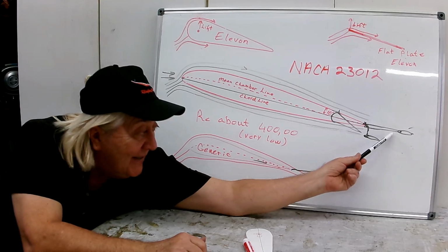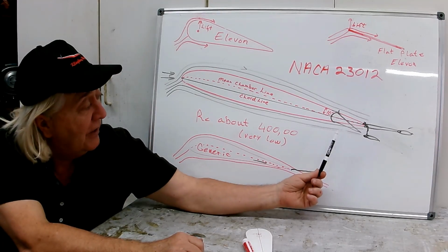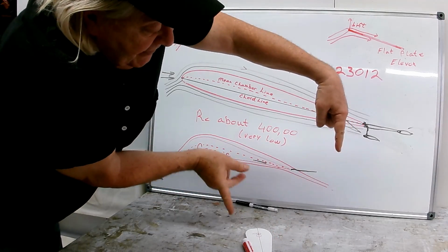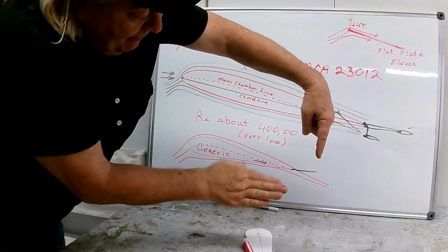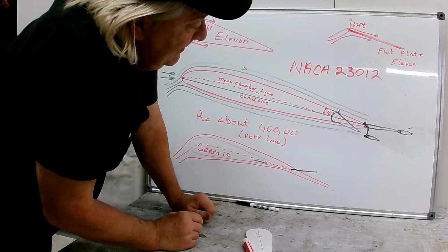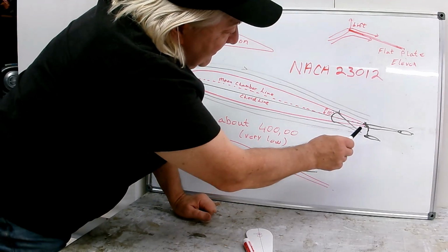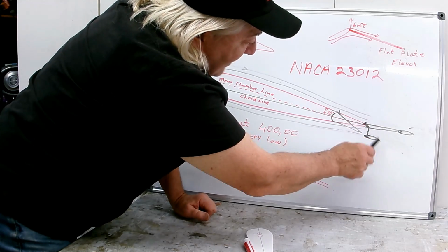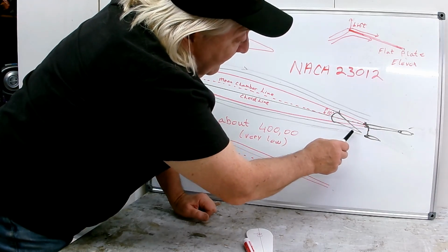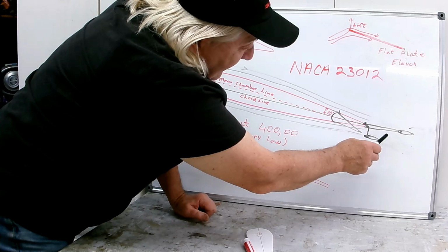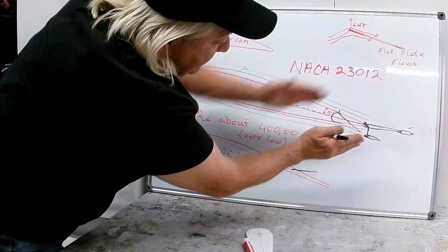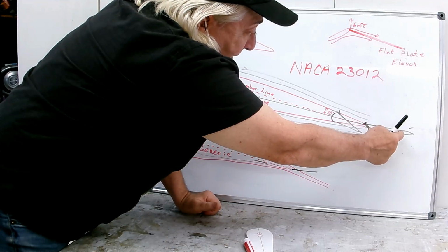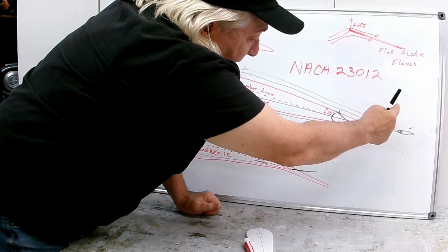Well, this isn't as effective as a flat plate. This would just be a pair of tubes, 2 pieces of tubing going aft with a flap going like this. And you're like, well, that's not as effective because the flow here, the potential flow field will want to go up in this gap or go down. You're going to get a lot of turbulence in here. It might be fairly straight, but you're not reshaping the potential flow field this way. You're just generating lift and drag back here, up and down.